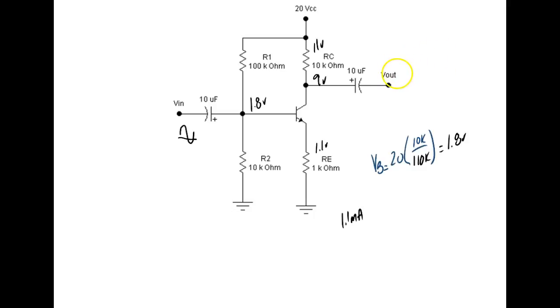So we know this guy over here is going to be 180 degrees out of phase. But when I look at it, it's going to be riding on top of my original bias, so it's going to be riding above a certain voltage. And we got to be real careful, because if this is 0 volts, if I ever let my gain drop past 0, we can't go by 0. So what happens if we try to overdrive this?